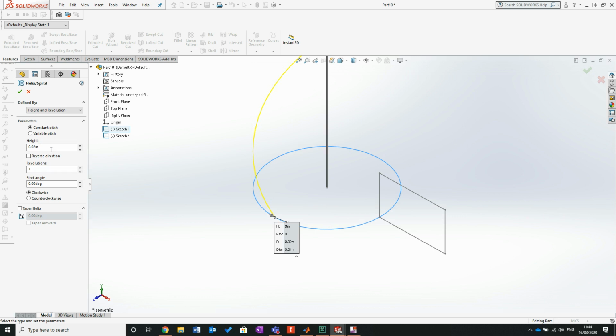Okay, never mind. So, because I don't know my pitches yet, I'm going to drop that from 20 mil to 2. Now, the issue is, if you look at that extrusion line there, these are going to collide. So what I'll actually do is just change that to 3. Again, I don't know what my pitches are yet. Wow, even that's colliding. I'll go 5 just to give me that offset. I can review it, see what it's like. If it's not any good, then we can change it.